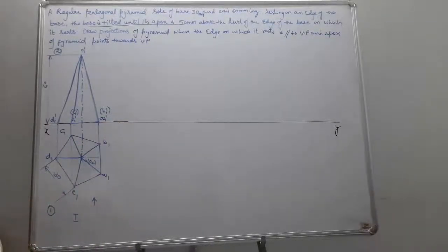All of you just try to do this stage 2. Try to do stage 2, how you are going to get your apex 50 mm above the level of the edge of base on which it rests, and how can you make it tilted.